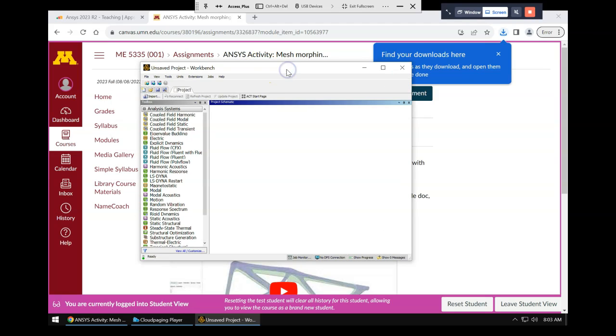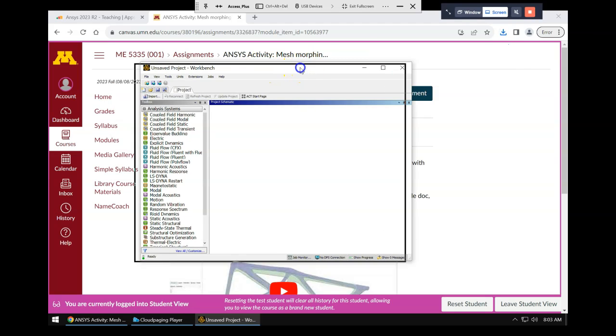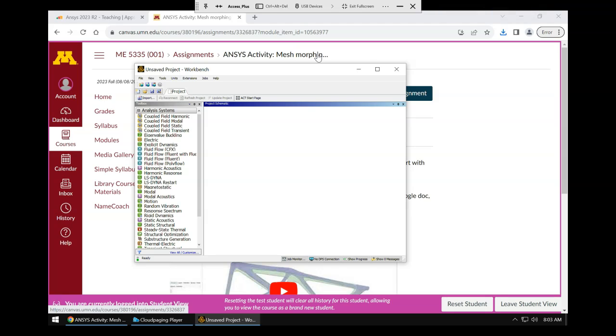So we saw topology optimization, and that works well if you have a blank slate design, trying to find an initial design point. What topology optimization is not good at is trying to modify an existing design. If you have an existing design that's pretty close to what you want, and you want some changes of dimensions or small amounts of change from that existing design, topology optimization is not necessarily great for that. So that's where we have shape optimization. That's what we're going to look at today.